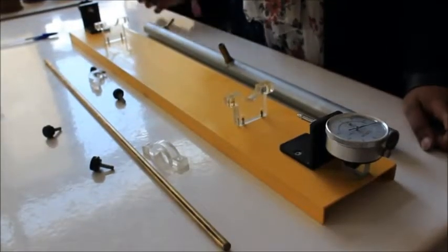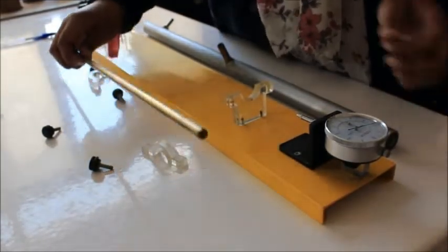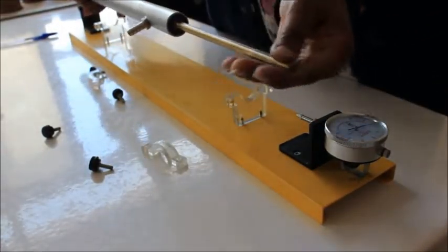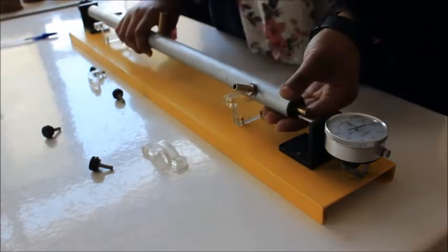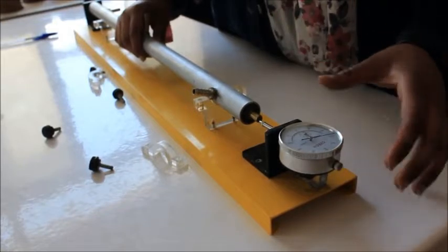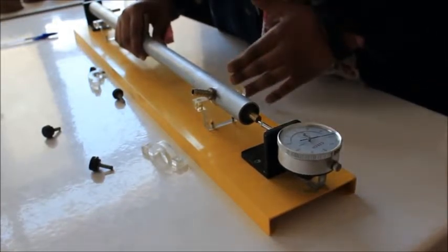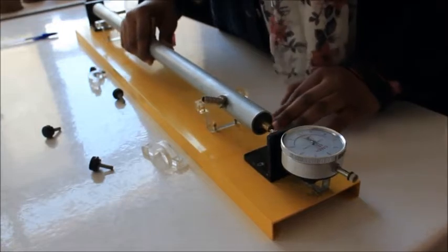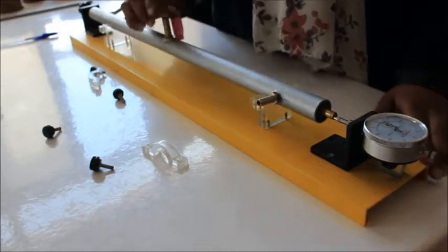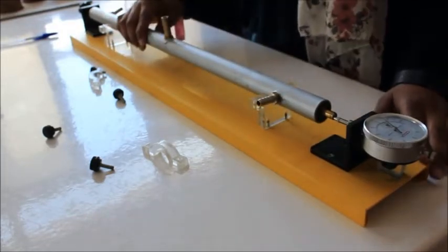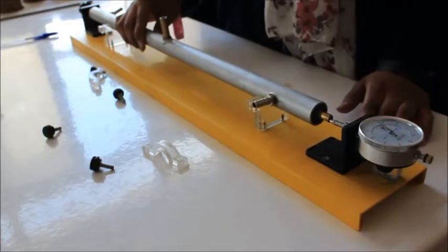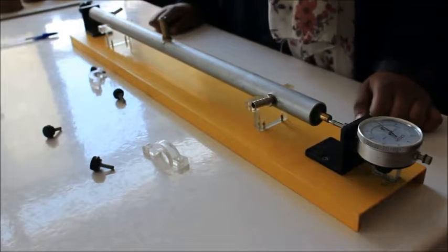To set up this experiment, first we have to measure the initial length of the material we have, like the copper here. Then we fix it inside the foam to prevent heat loss. Then we fix it inside the apparatus we have. The gauge here calculates the difference in length when the material expands and pushes it, so it produces a change. Then I fix the heat source from here, and we measure the initial temperature and final temperature to get the delta T. Then we substitute all the variables inside the equation to get alpha, the linear expansion coefficient.